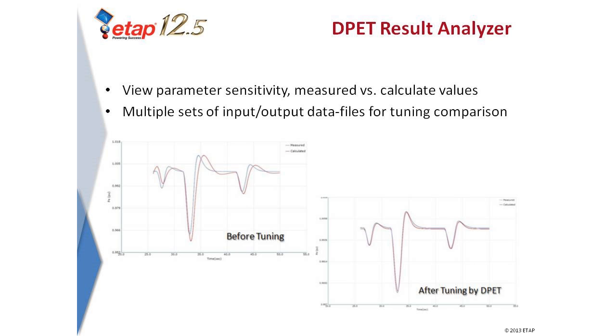Deepeet adds an intelligent automated layer of time-saving capabilities. Combined with ETAP user-defined dynamic modules, Deepeet automatically adjusts appropriate parameters so simulation responses match actual field measurements accurately in a matter of minutes rather than weeks. Not only can ETAP's dynamic parameter estimation and tuning modules save you time and money, Deepeet is especially useful for power plant model validation, as mandated by the North American Electric Reliability Corporation, also known as NERC.